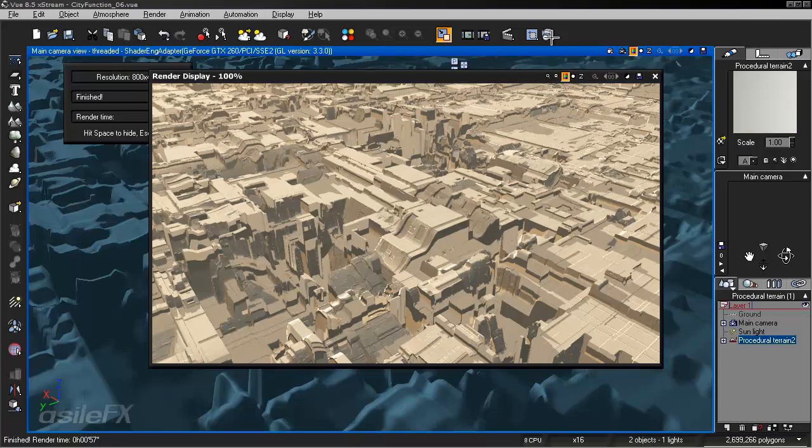And I did just modify a few things because the render was going to take too long. I turned down the quality boost to 2 instead of 4 and deleted the secondary material and turned down the frame size because it was going to take more than an hour to render that other one. Partially because of the material blend, but mainly because of all of the extra geometry needed to be created for the quality boost.